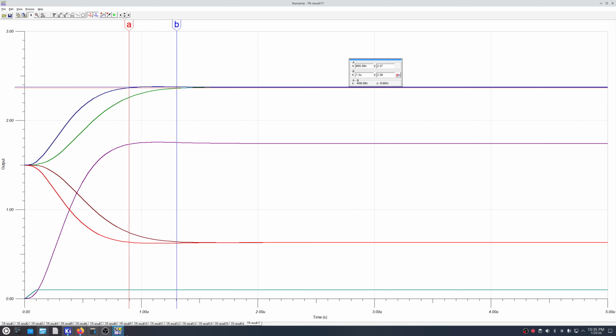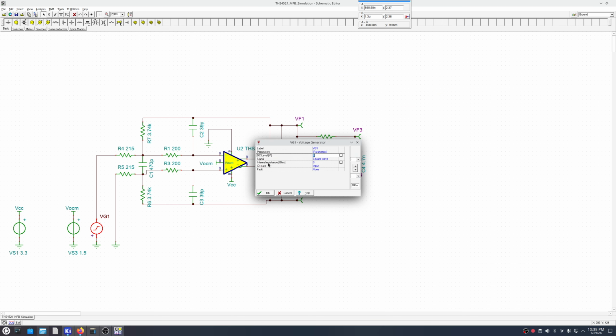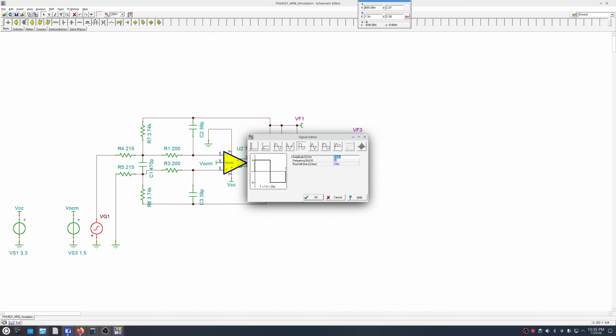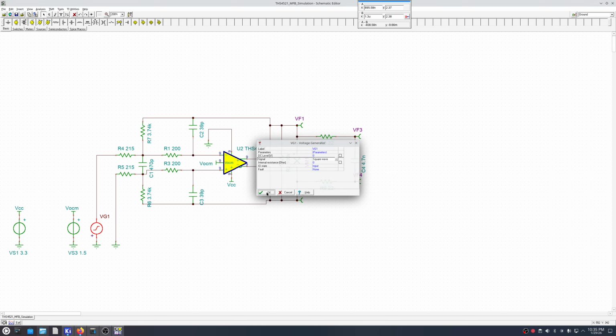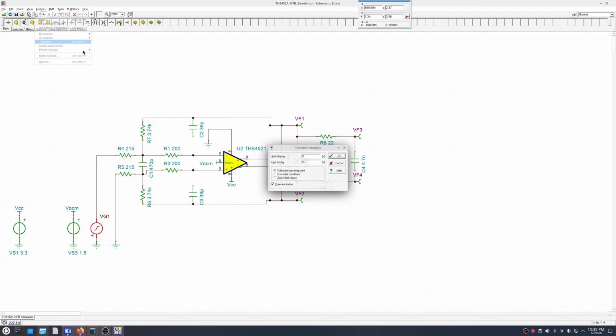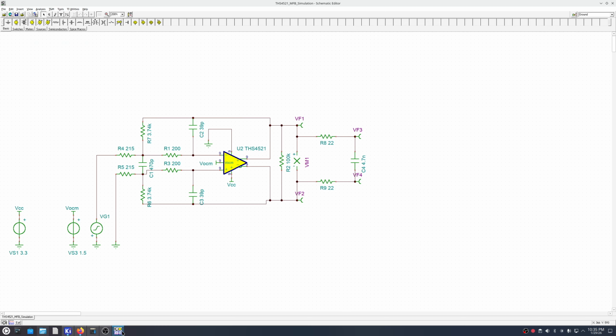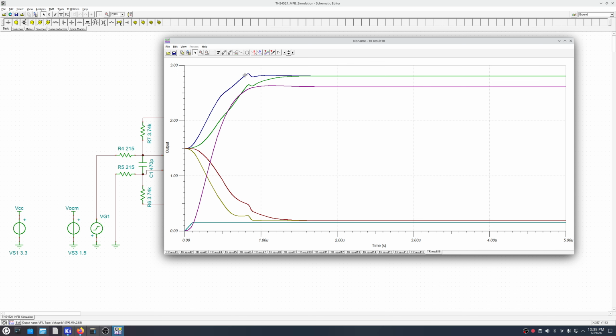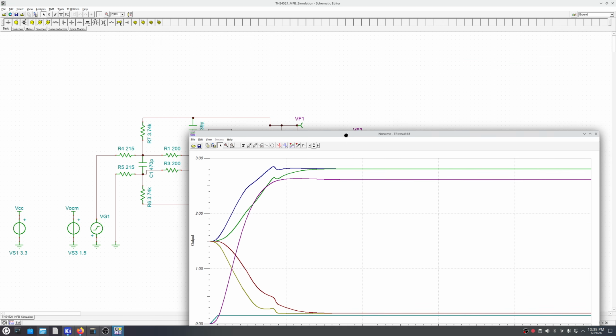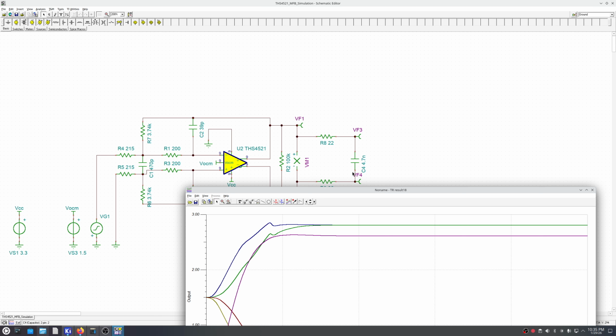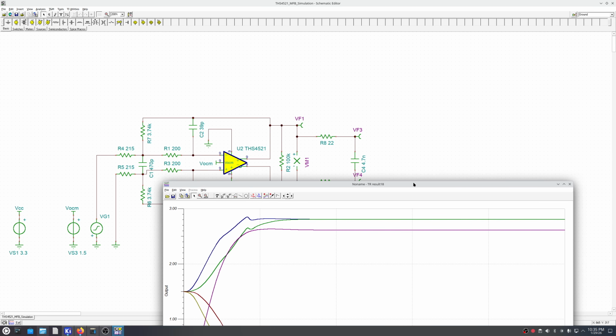Well, whatever. Now it doesn't show that, but here we have the differential output from the amplifier, and like here I was setting only 100 millivolts there, and then if we go up, we can try like 150 millivolts, and then we can simulate it again. So we are already seeing something odd here, and what is happening, the charge bucket we have here, it will mess the circuit at some point.